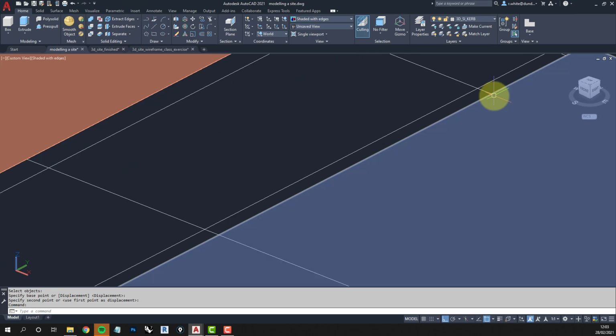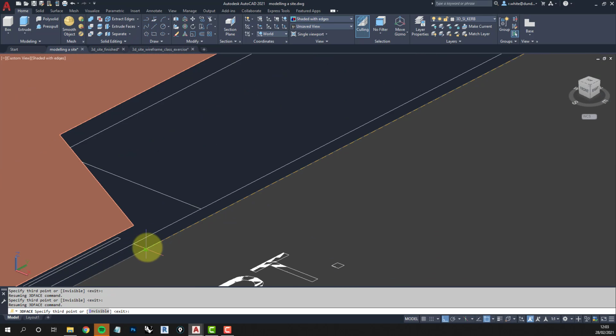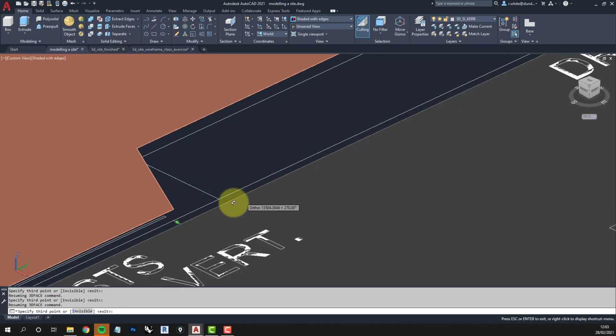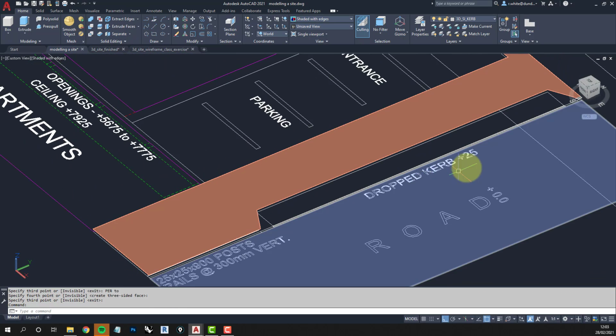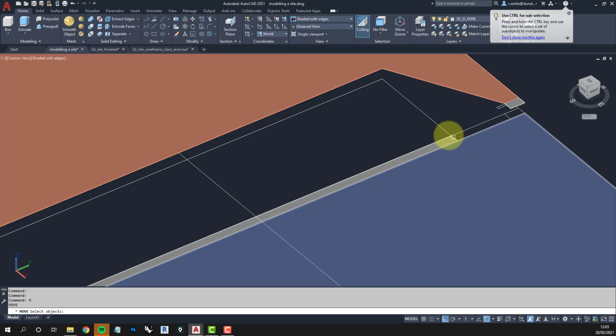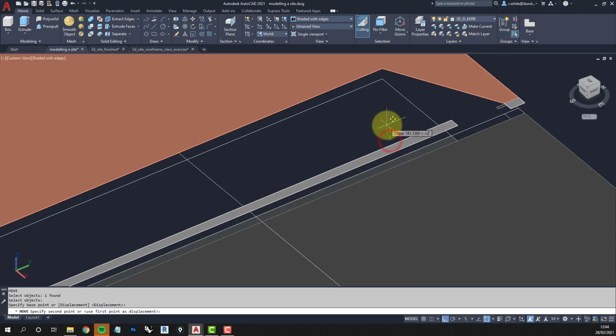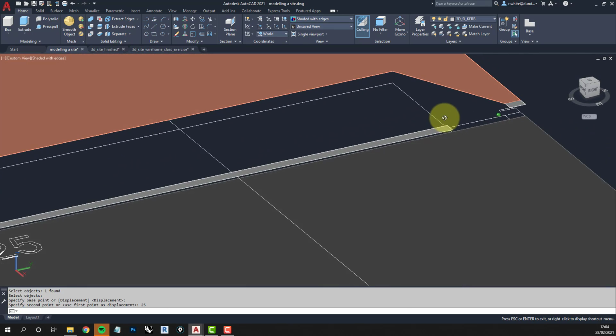Okay, we've got the bit in between is only 25 millimeters high, so we'll 3D face it where it's sitting. So it's a long thin shape. Okay, we actually need to come perpendicular to here. Okay, and then that goes upwards just 25 millimeters. So it's move, pick the surface, enter. Base point can be anywhere, and we're going up 25. Okay, it's starting to take shape now.